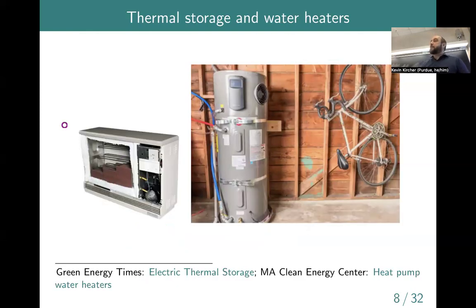We'll also talk about heat storage or thermal storage, which can take a few different forms. This is a very simple type of thermal storage, which I guess people would call something like a box of rocks. These are basically bricks, particular bricks chosen with materials that have good capacity for storing heat. And then these U-shaped things here are electric resistance heating elements. You run current through them and they get hot. So you take electricity into this device, you heat up the bricks.